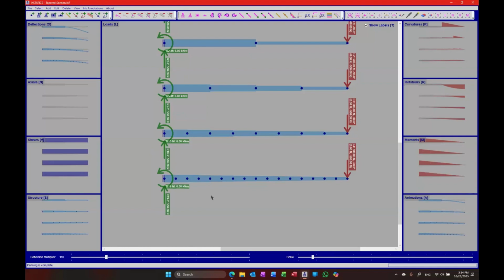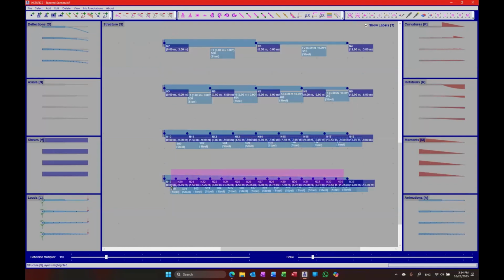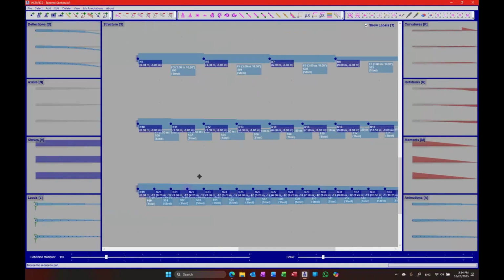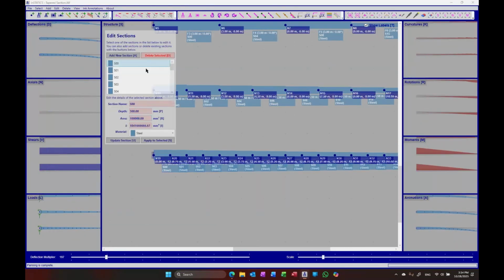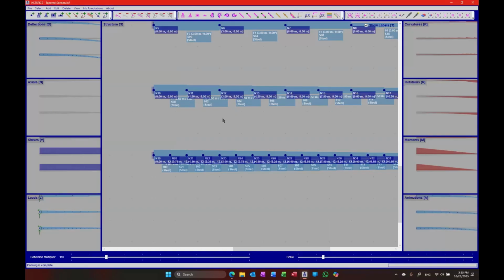Here I divided it into, I think, 16 sections. Yes, I divided into 16 sections where the depth and the section properties are changing, as they should, right? As the depth is changing, the second moment of inertia is changing as the fourth power of it, the real value at those sections.